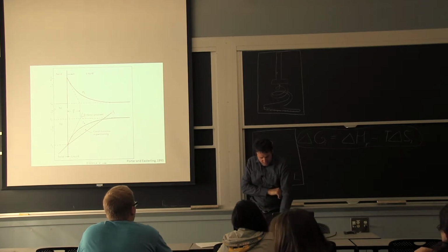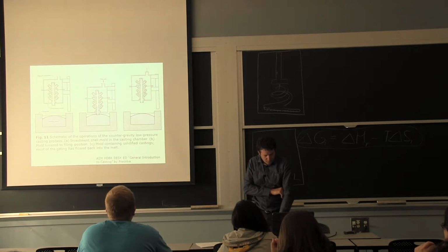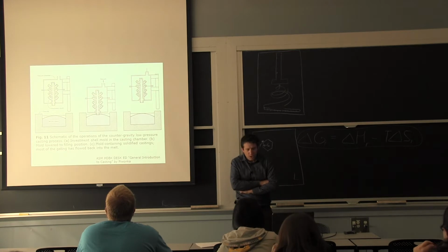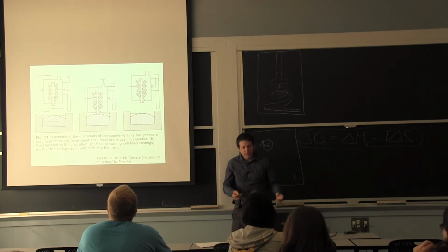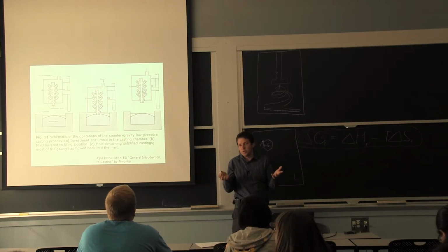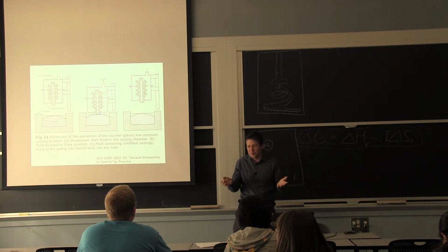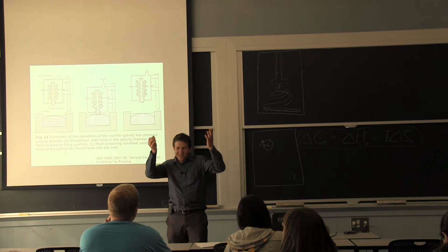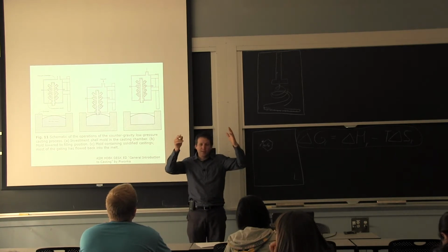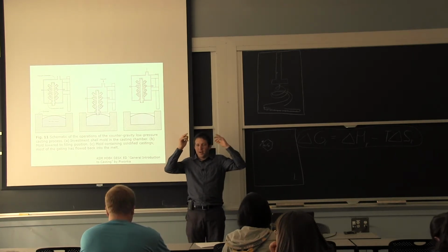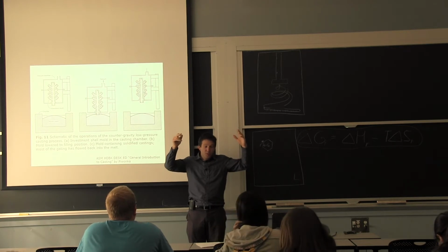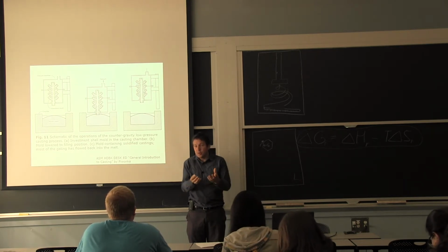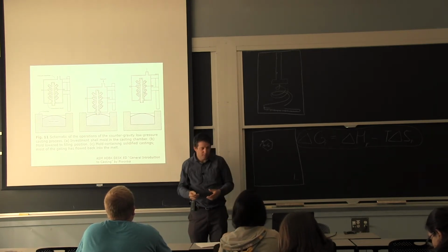If you're casting, and that's where we're going, you end up heating your metal above the fusion temperature. And that one we call the superheat. Everything is super. So superheat is the temperature above the melting point of the alloy. It accounts for some temperature decrease by the contact with the mold as you're feeding your liquid metal.